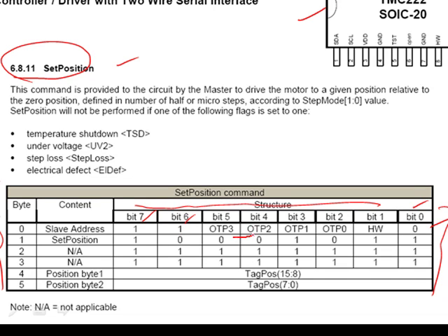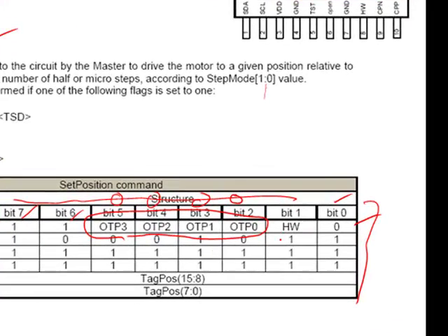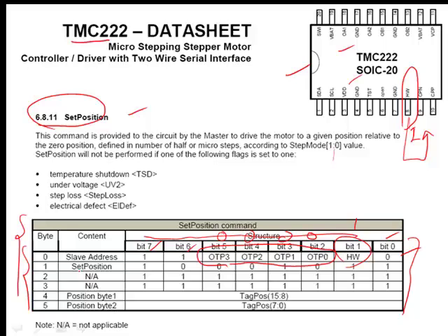These next 4 bits here are one-time programmable bits. That's what OTP stands for. You can program them to set this device to have a unique address. Let's assume that these bits are all programmed to 0. This next bit corresponds to a pin on the device that can be tied either high or low. Let's assume that this is tied high, so that this bit is a 1. Then these next 3 bytes specify the set position command.